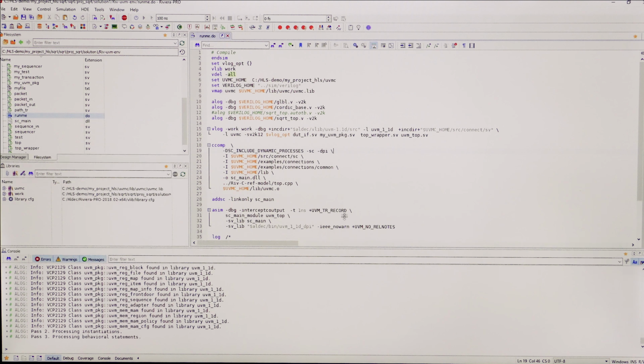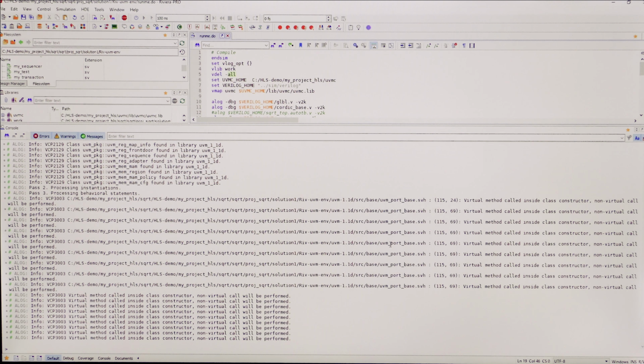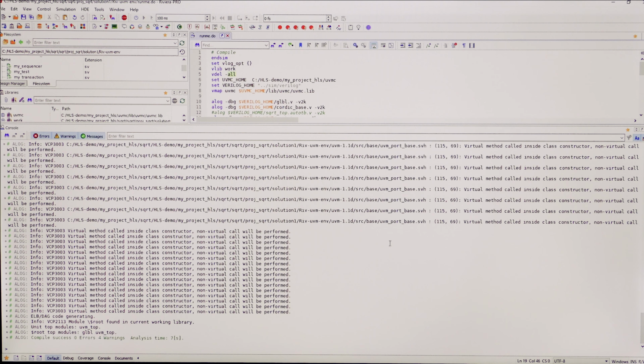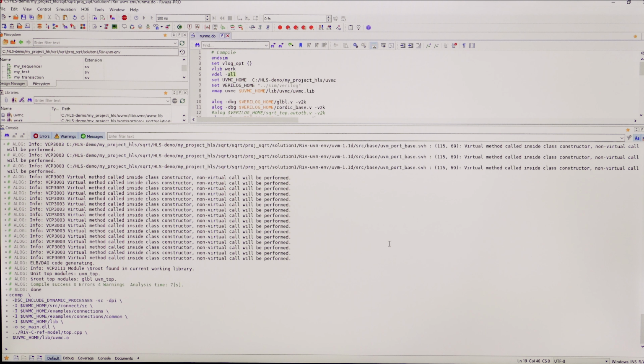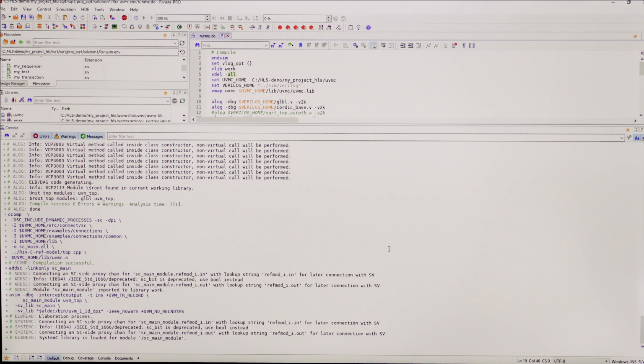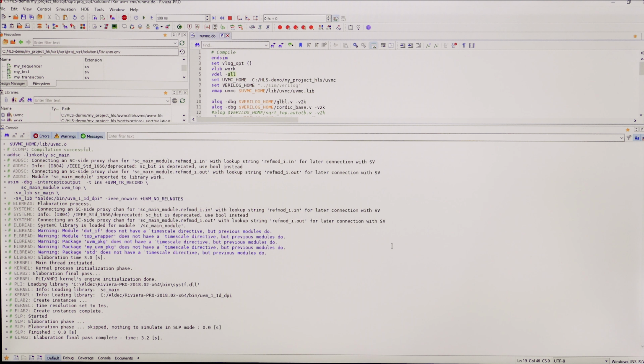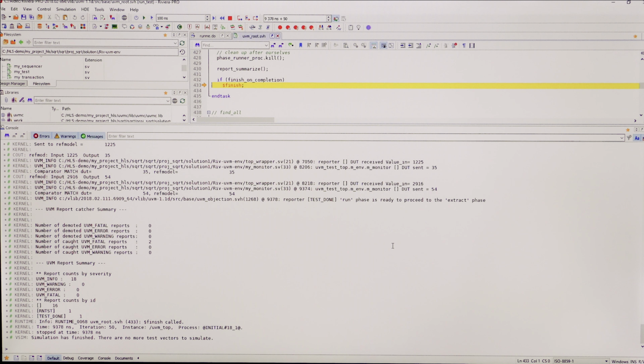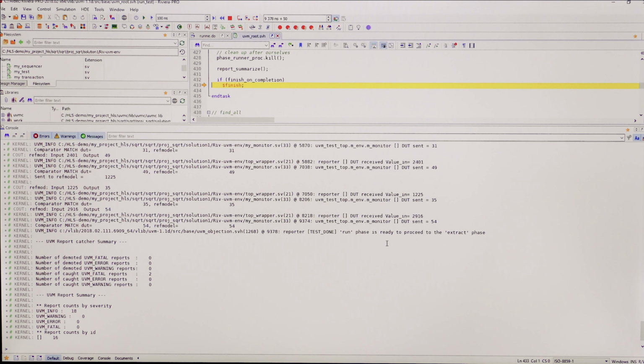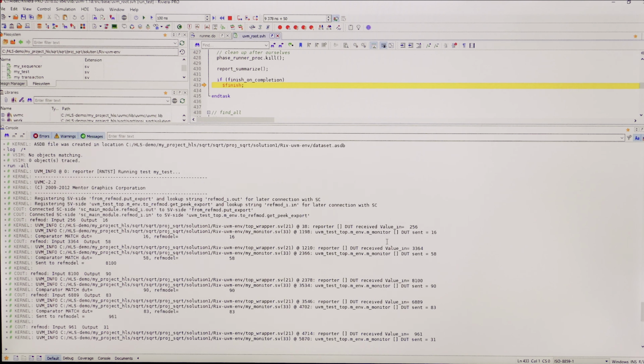While this is running, let's talk a little bit about the various things that we had to do. On the C side and on the UVM side, we use UVM Connect to do the connections between C and UVM, and we use the UVM Connect library to achieve that, which is based off of the DPI library that is used in SystemVerilog. The example has finished running. As you can see, we are comparing the reference model or C model output with the output from your DUT to see if they are matching.